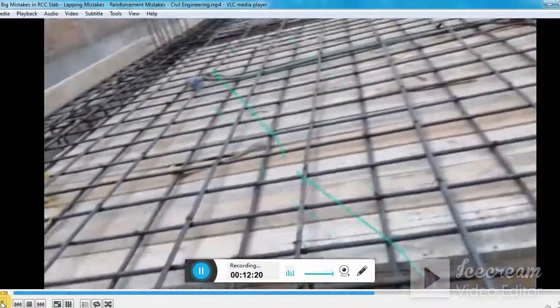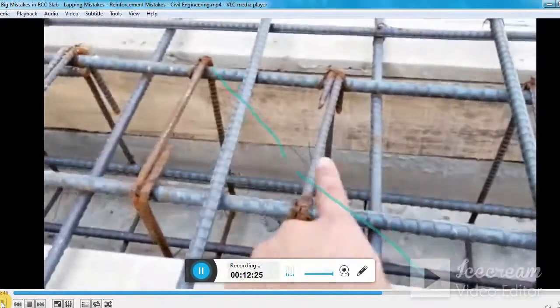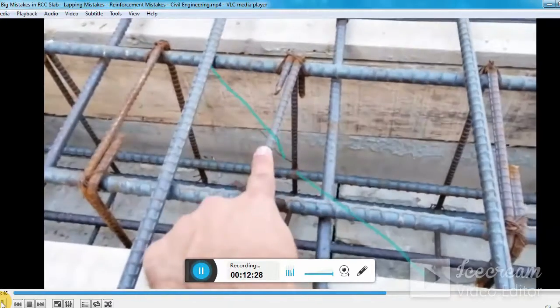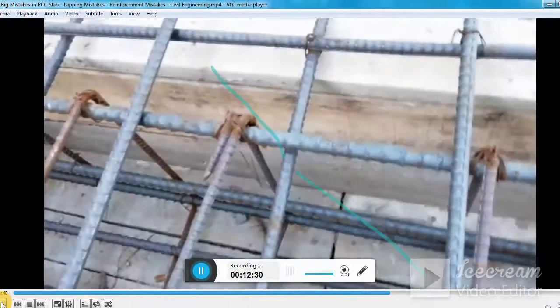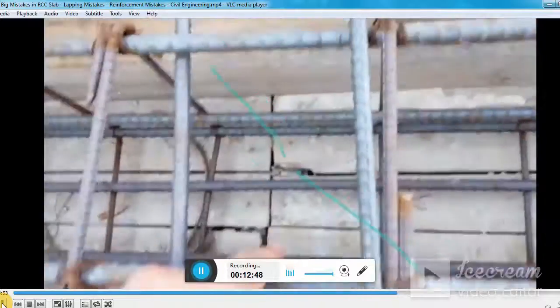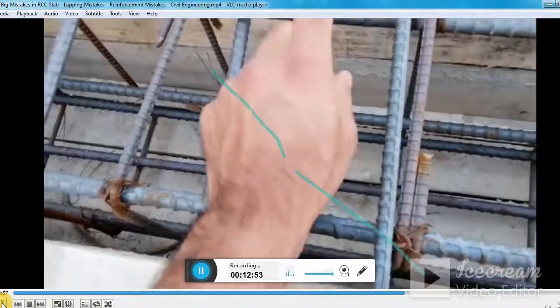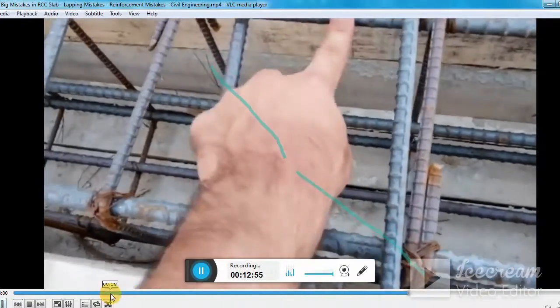But here is the other mistake. You can see here stirrups, whose diameter is 6 millimeter. This is the RCC beam. How can you say the stirrup diameter is 6? Top beam, yes, and in total 7 steel bars are used here, 3 at this side and 3 on this side. One is at the middle, and each steel diameter is 16 millimeters, so it's okay.